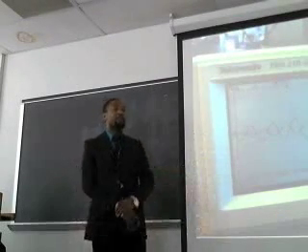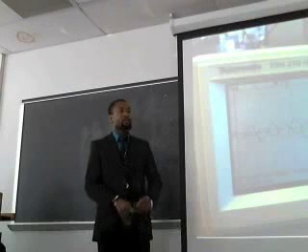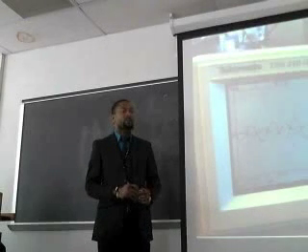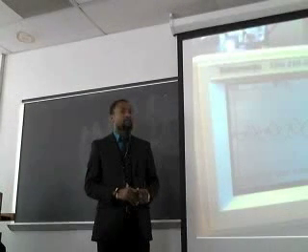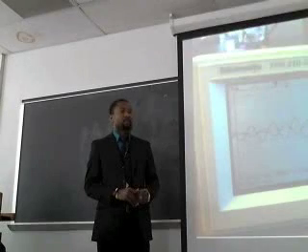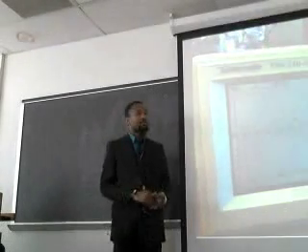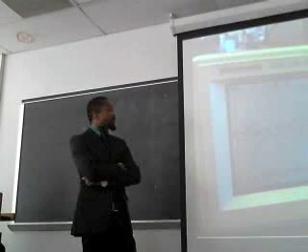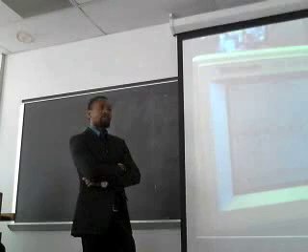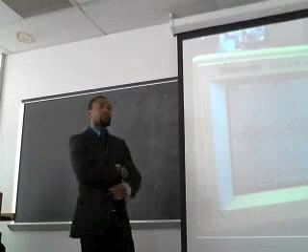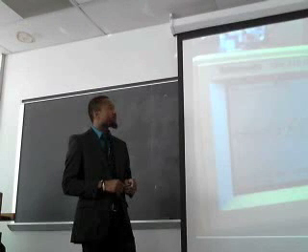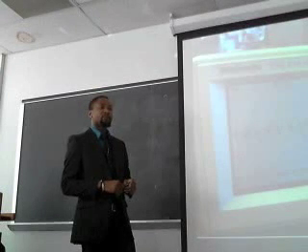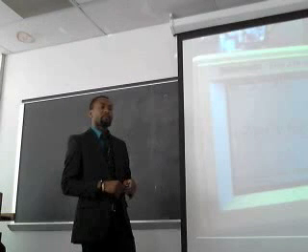So something is funny, because your very first input is three phases and all of them are 120 degrees apart. So your output should be the same. But right now you have one high and one low, so there must be something either in the PWM which doesn't give you the high. Try to fix the PWM for the second phase, because maybe it is not correctly shifted. Or you can make each one single phase, store the first one, store the second one, and superimpose them to see if there is actually a 120 degree phase shift and the same magnitude.